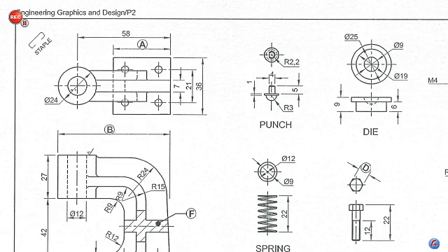You must add the distance from this center until the arrowhead, which is the radius, and that 24 gives us the diameter, so divide that by 2, which is going to give you 12. So 58 plus 12 will give you 70 millimeters. That is the 58 plus the radius here of 12 gives you 70.